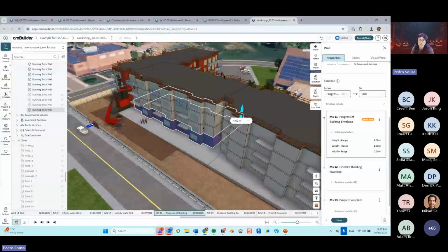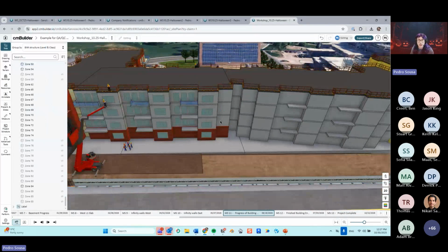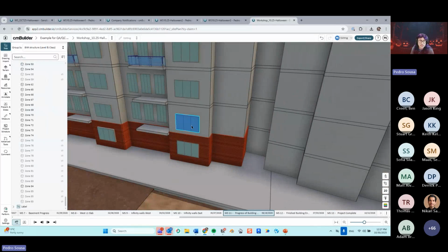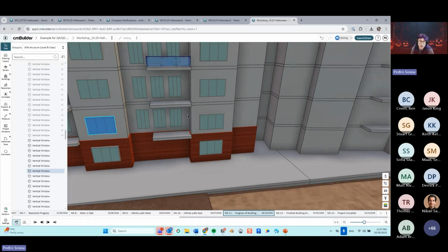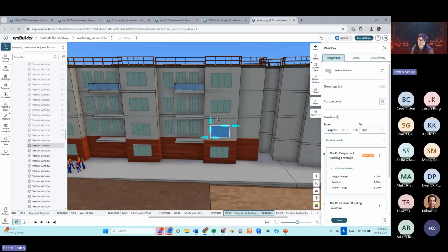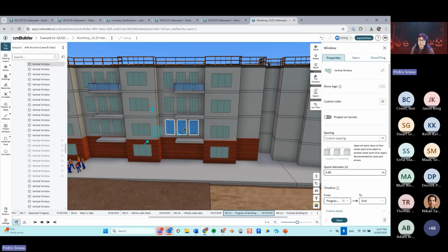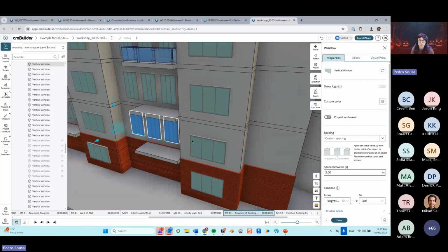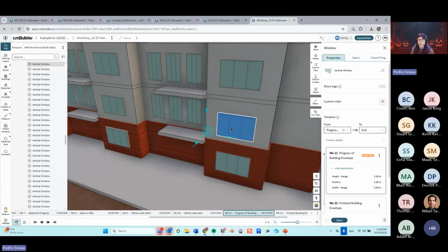Oh, and one thing about the windows that you see over here, again, also things that you're going to find in our library. So the windows, you can place them as individual panels like this, right? So just having them at the same height and things like that. And to place them at the same height, you can simply copy paste whatever elevation you have, apply to one and then apply to the other, or you can draw them as a line. So when you do these as a line over here, for example, this is the same object, but this one is placed as a point because we wanted to just do one with that width and height and whatnot.